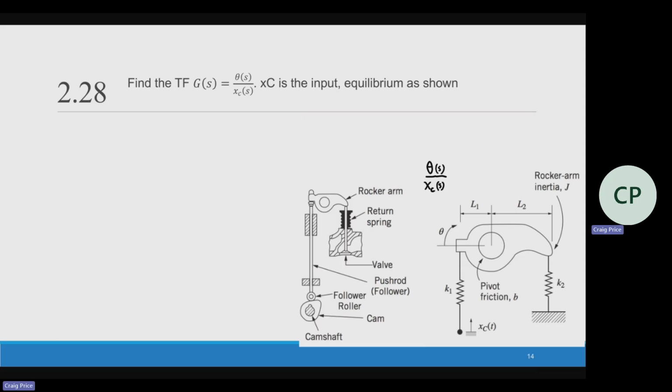This is what I'll say for the body diagrams. If you have anything that's round like this, it is not a force. That's a torque. Anything that's rounded. But if you have something that's a force a distance away, you can label that as a force. But anything round should be a torque. We're going to do sum of torques.